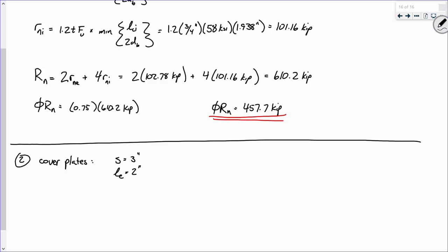Okay? Now, that's the first point I want to make. Here's the second point I want to make. Now, the thickness. Okay? There's 2 ways of going about this. One way is we could say that the thickness is 1/2, compute the capacity, and then at the very end, multiply by 2. That's one way of doing it. The other way of doing it, which is what I think is the easiest way, is to just say the thickness is 1 inch. I think it's a lot easier to do that now because when you're down the line and you've already done one of these and you get into that repetitive, well, it's still 2 edge bolts, it's still 4 interior bolts, so now there's phi. It's very easy to forget to do that. So right off the bat, I'd say, you know what, let's just take care of that now and not worry about it. Let me just say this. You can do either one and you will get the same answer. I just think it's easier to get that out of the way now.